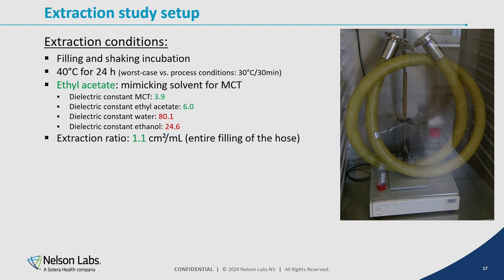For the study design, we again used the filling and shaking incubation method, where the tubing was entirely filled with the extraction solvent. We used in the first trial 40 degrees Celsius for 24 hours, so the standard conditions for short contact materials. They are definitely worst case to the process conditions, but we decided to go with them because they are stipulated in USP 665, and you cannot do less worst case testing as stipulated in the document,